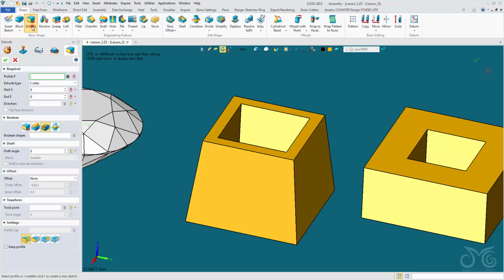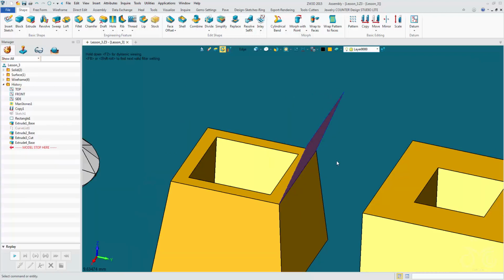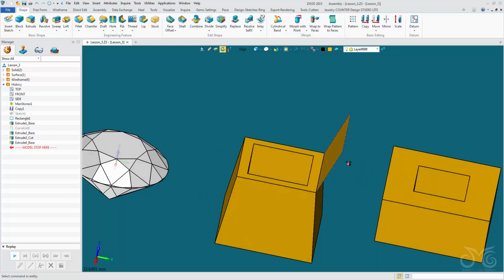So extrude again. I'm now going to show you a line extrusion. So we can extrude a curve or an edge. Let's extrude an edge, this edge here. We left click, you can then extrude. Let's give it a one-sided extrusion. Extrude up. Now an extruded edge or curve like this will create a face. We can give it a draft, which is going to change the angle of extrusion. Confirm. And we have a face. We've created a face here.